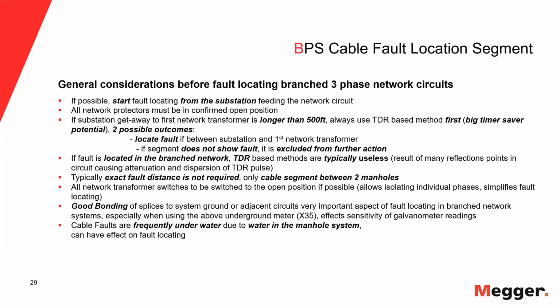You don't have to open manholes. You can pick up this electromagnetic pulse above the ground, and you can see that makes it very nice and convenient. You don't have to go in manholes. You don't have to pump manholes out and do all this good stuff. But because you do it above the ground, the signal is already reduced. So you need a very high sensitivity signal unit to pick the signal up.